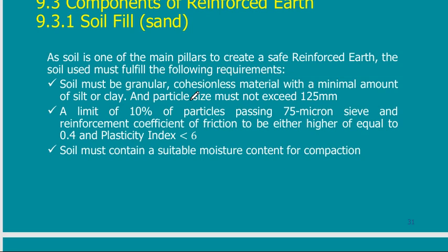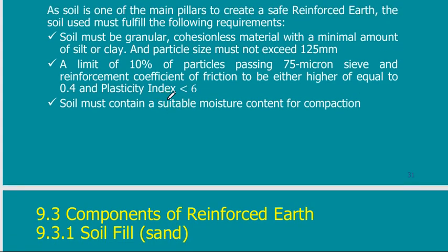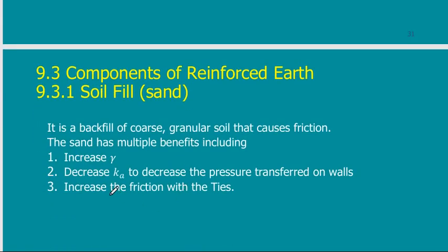You should use sand with a very limited amount of fine particles, maybe less than 10%. So it is similar to the sand that you use for normal compaction in big projects.